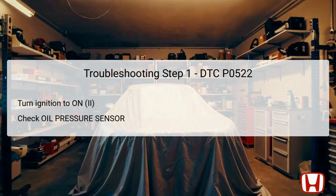The first step in troubleshooting DTC P0522 begins with turning the ignition switch to the on position, labeled as 2. This action is crucial because it powers up the vehicle's electronic systems, allowing for diagnostics via the Honda Diagnostics System, HDS. Next, you should check the oil pressure sensor's data list using the HDS.